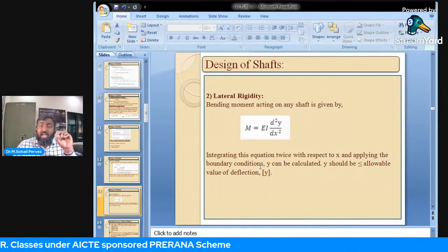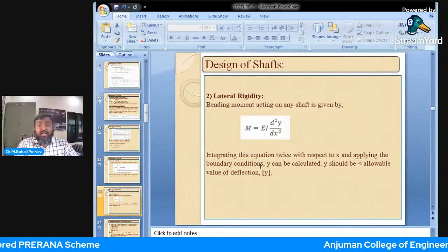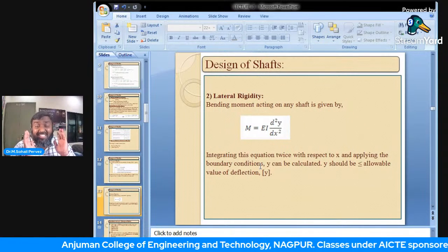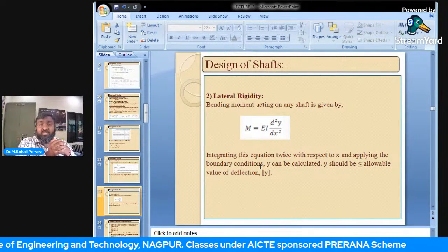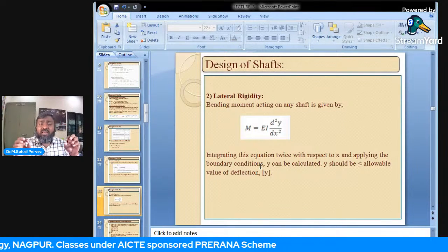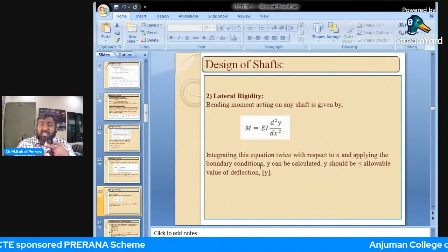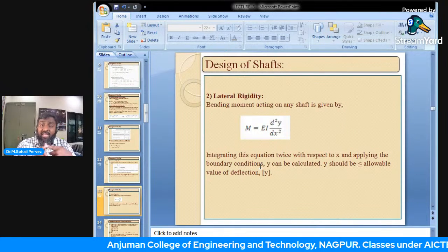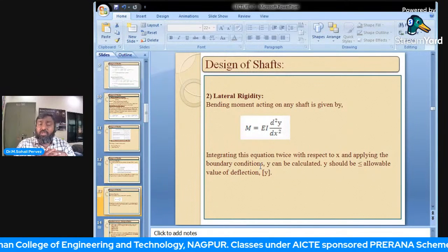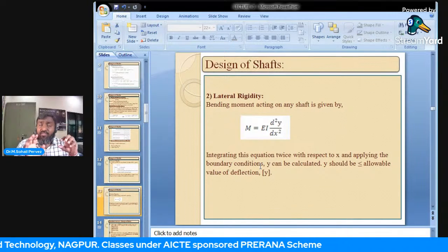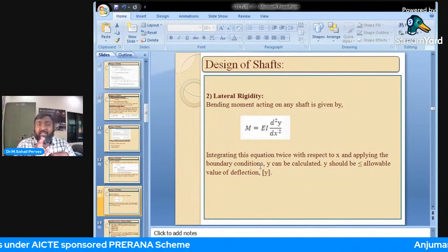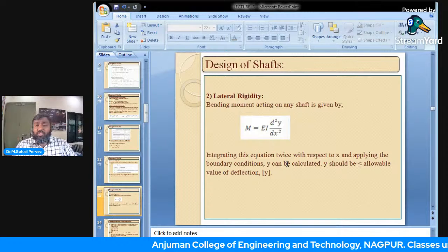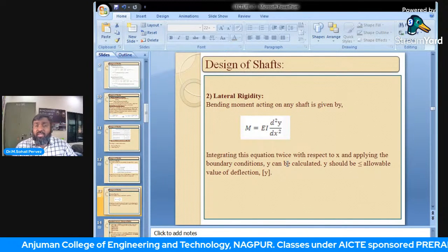Again, it will change the distance, and if the shaft gets permanently bent, then whirling may occur and the bearing may get damaged. Mind well, what I am discussing now is the shaft. If the shaft gets a permanent, even slight, deflection, obviously at higher speed the danger of shaft breaking or whirling will increase, and the severity of that damage will be greater if it is bent. We don't want our shaft to get bent. That's why this element should be laterally rigid, so that there should not be any permanent bending.